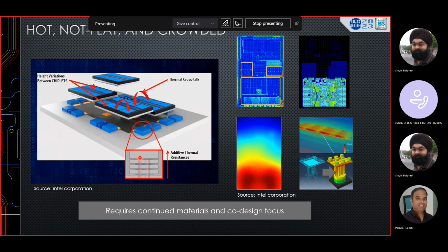For another application, I can say that 80 and above is my hotspot, because above 80, though theoretically devices are not going to burn out, I will be above my leakage target. So it depends on the design style that Rupesh is trying to talk through, and it's based on your type of design, type of application. Let's say you are running a laptop. You don't want your lap temperature to be more than 35, 40.